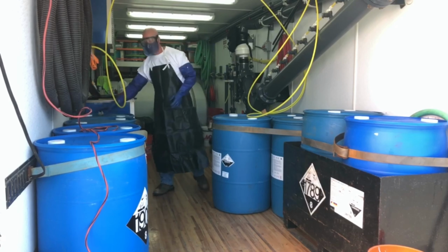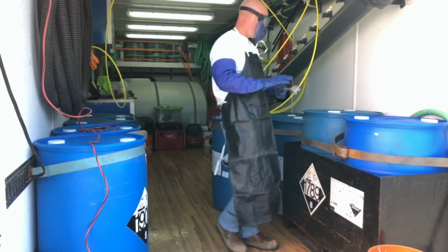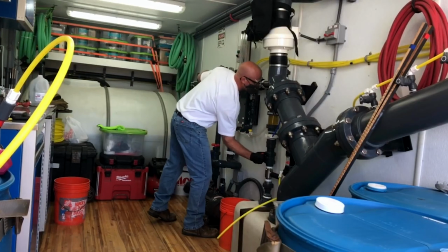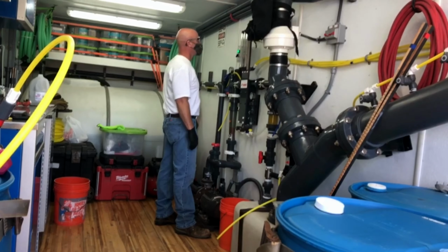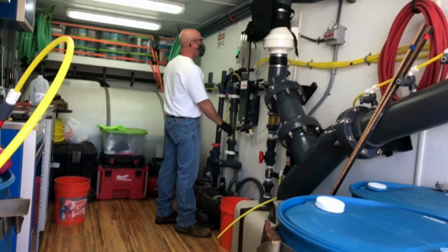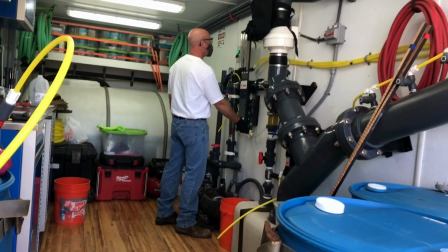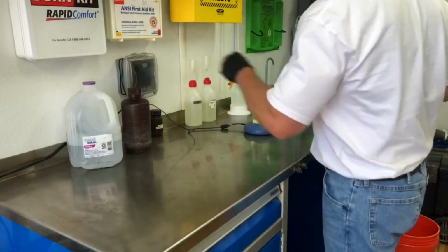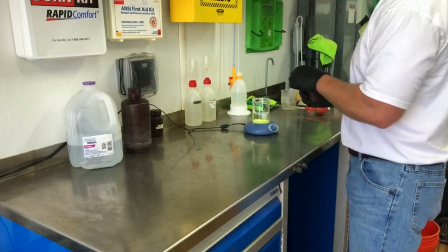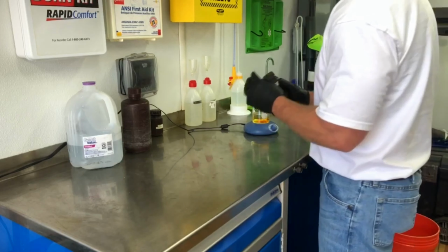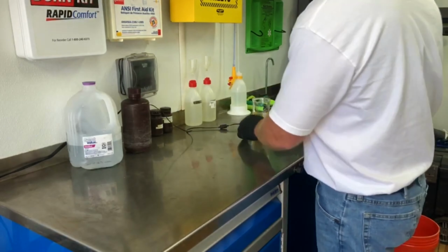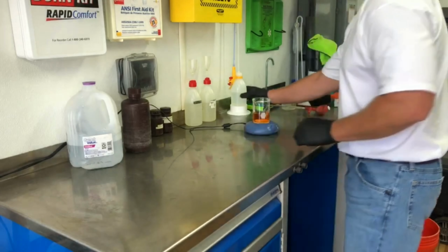Once on site and fully set up for the chlorine dioxide application, a 3000 ppm solution of high-purity ClO2 will be generated in the truck and pumped into the system being treated. Careful attention is paid to regulate the flow and consistency of the chlorine dioxide solution. Chemical tests are taken to ensure the concentration is steady and effective. The entire application process usually takes 3 to 5 hours.